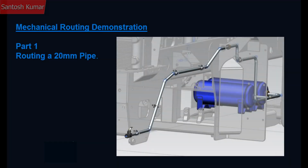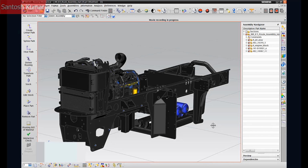Part 1 of the presentation will show NX routing being used to route a 20mm air pipe down the side of a frame. This presentation is designed to show the various features of NX routing and some of the methodologies used to complete a route. The pipe will be routed from air tanks in the rear to a position in front of the frame. U-clamps have been placed in the assembly to locate the pipe.